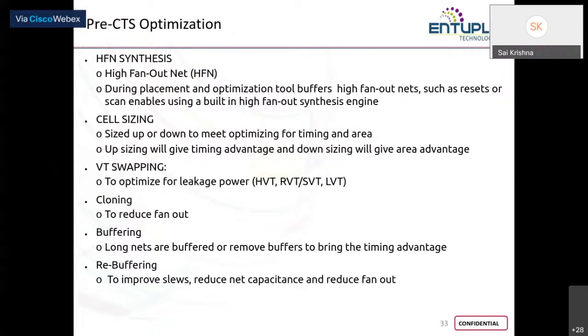So these drivers, when they have to face too many fan outs, depending on the driving strength of your driver, it may or may not happen. If it happens, well and good. But if it is not able to drive the high fan out, then your data will not be propagated further properly. Okay. So that is a problem that arises with high fan out net.